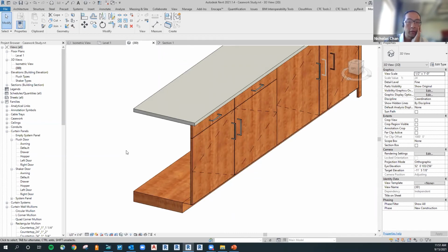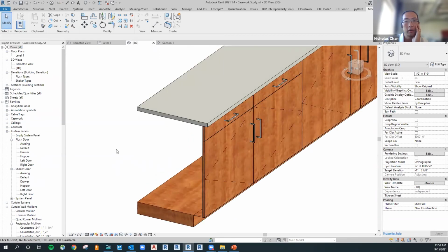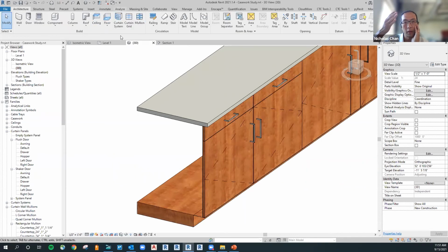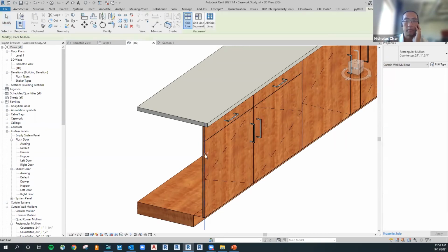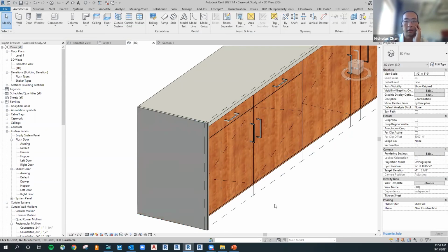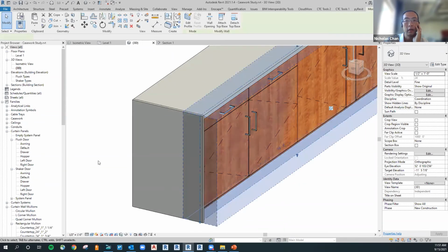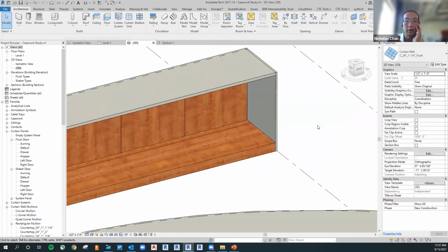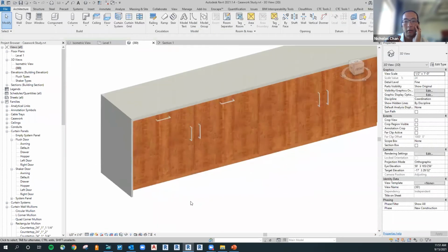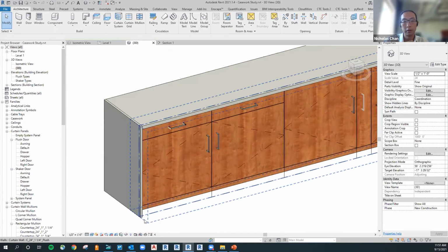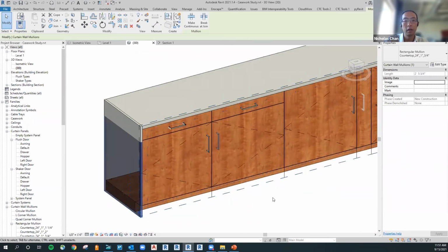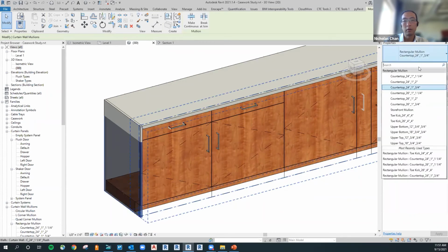It's a vertical mullion that we use. That's the full depth of the cabinet, and it either stops at the bottom of the grid of the toe kick, so you don't have an end panel that goes all the way down if that's not what you want, or it can go all the way down from the underside of the countertop. Yes, something like that. I believe the question is how do we deal with that end condition? Which occurs all the time. Using mullions, you can toggle the different joint conditions here, the thickness of it, to get generally what we find at these conditions.